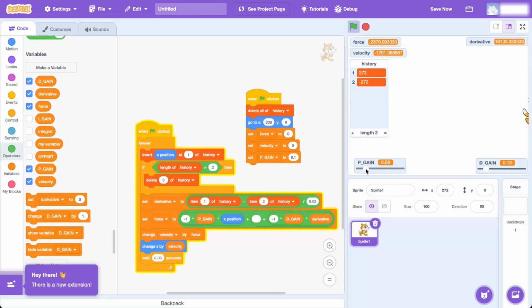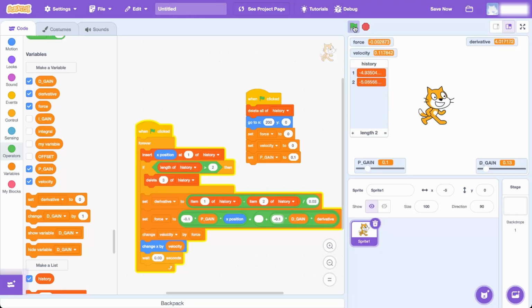So what seems to be the problem here? Oh, our gains are enormous, so we'll only need to be about 0.1 and negative 0.1 here. You can see that it stabilizes near the center without the ringing. If we loosen this gain on the derivative factor, we can see there's some shake as it overshoots the first time but slows down enough to be caught. If we lower it even more, then there's even more vibration.